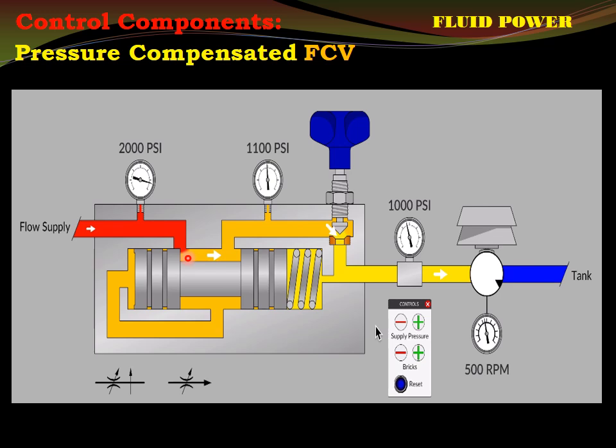But no matter what the opening is, upstream to this opening, pressure will always be relief valve pressure, because it is coming from the pump. As this opening is being controlled, definitely the extra amount should pass through the pressure relief valve, and thus the pressure upstream to this opening must be the pressure relief valve setting, say 2000 psi.